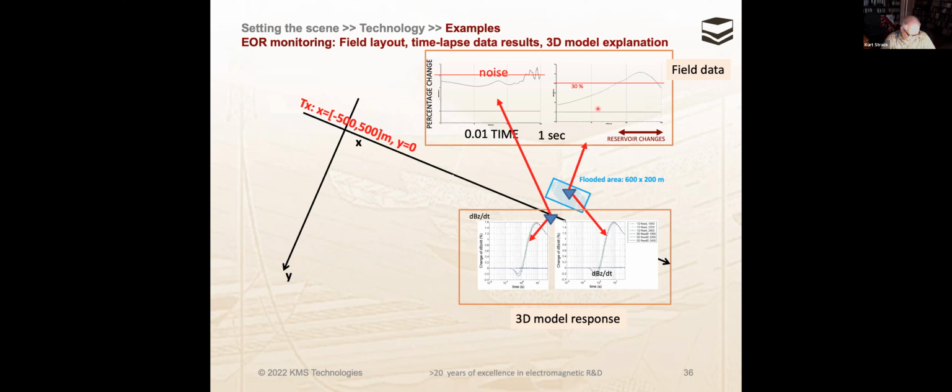And that may be due to current channeling of the pipes. Well, there's hundreds of horizontal pipes, and in fact, the water was injected from 6 kilometers away horizontally at 2 kilometer depths. So we modeled the casing, and I came to the conclusion that the casing modeling we see in the literature is wrong, because we use realistic values that we got from the feasibility of through casing resistivity tools, and we could not verify the pipe influence in the data. We see pipe influence, but not in the same bandwidths.